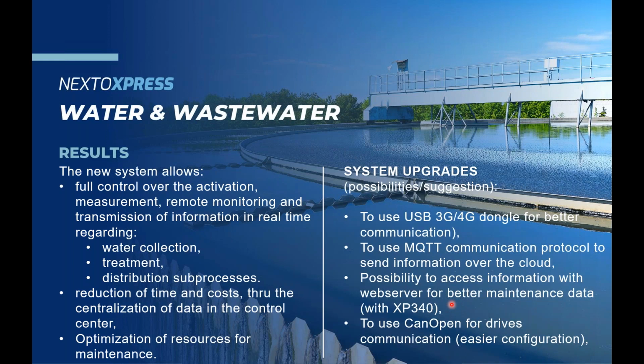And use CANopen instead of Modbus RTU to communicate with the drives. I'm a big fan of CANopen. It's much faster, much more reliable, and much easier to configure than Modbus.